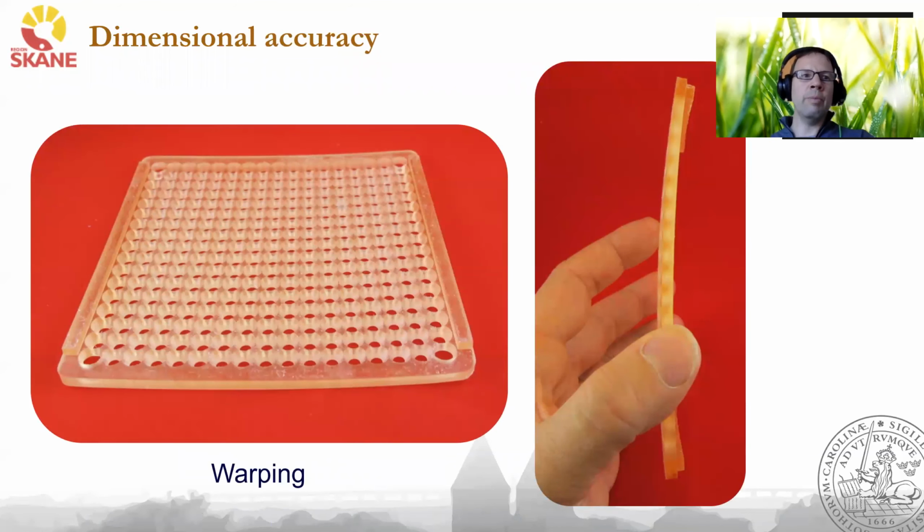So here's a plate that we printed. When it came out from the printer, this is printed on an SLA machine. So directly after it's printed, it's washed in isopropanol, and then you continue to cure it in UV light. When it came out of the printer, it was completely straight. And dimensional accuracy is really high, and we're close to the building layer of 0.1 millimeter or so. So it's excellent accuracy. And then after curing, the plate bent, as you can see in this.